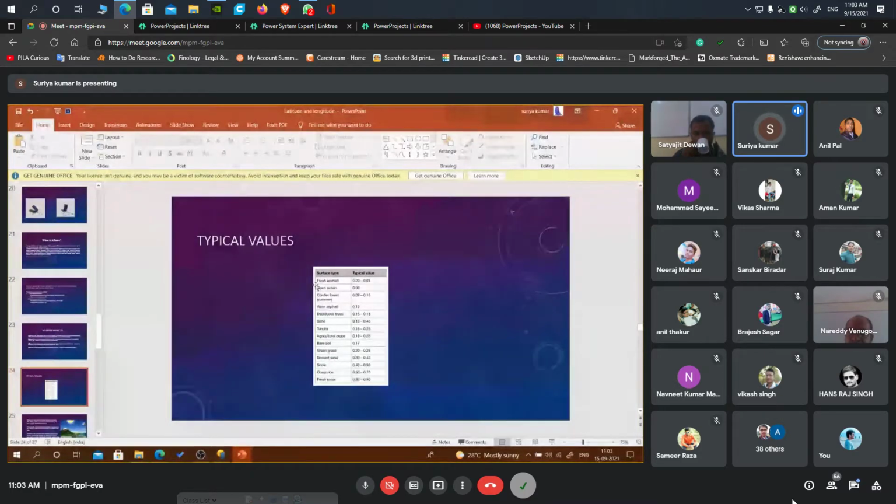They are giving values for albedo. Sand, for example, is 0.15 to 0.4. Depending on this value, the reflection from the ground will vary. That reflected irradiance is going to fall on your panel, which means you can generate much more energy. From reflected diffused waves also you can generate energy.